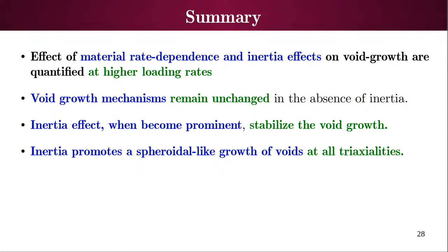So in summary, I can say the effect of material rate dependence and the inertia effect on the void growth are quantified at higher loading rates. Void growth mechanics remain unchanged in the absence of inertia. So mechanics does not change if inertia is not present. When inertia effects become prominent, they stabilize the void growth.